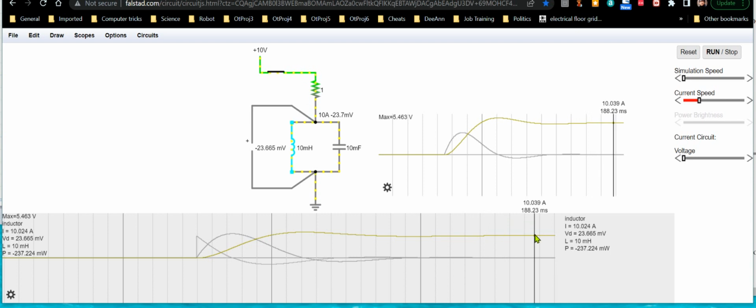It's got that energy stored in its field because it's got a current going through it, and it's an inductor. Alright, and it's got zero voltage. That's how you know an inductor is charged: its voltage is zero, but its current is at max. That means the field is fully charged. Conversely, a capacitor is discharged because its voltage is zero, and there's no current flowing through it. So it might as well just be sitting off in your toolbox somewhere. In its current state of affairs, it's not doing anything.